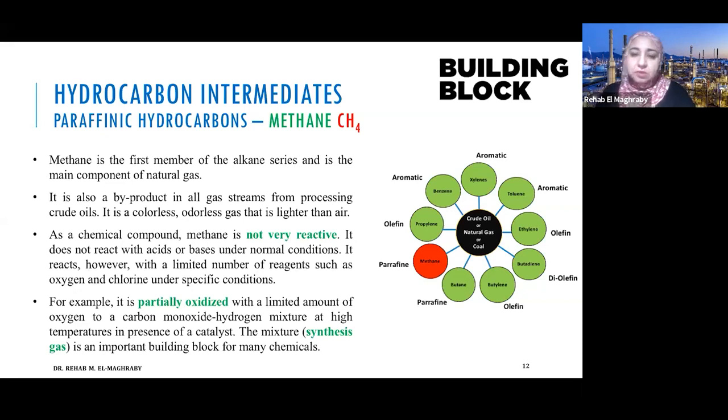Okay. So syngas actually is one of the important building blocks. Syngas is also a way to convert coal to liquid. Coal or biomass are converted to liquid hydrocarbons through Fischer Tropsch from the combination of syngas, which is CO and hydrogen. Okay.